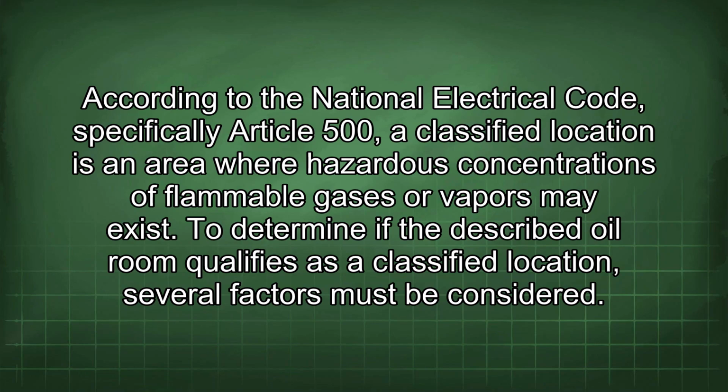According to the National Electrical Code, specifically Article 500, a classified location is an area where hazardous concentrations of flammable gases or vapors may exist. To determine if the described oil room qualifies as a classified location, several factors must be considered.